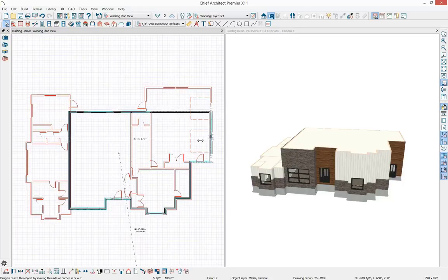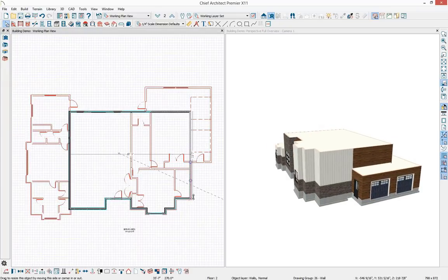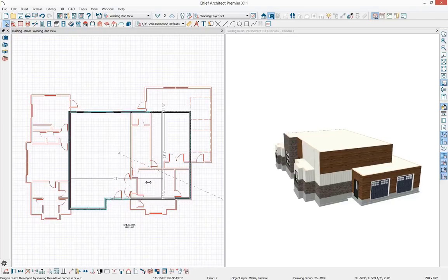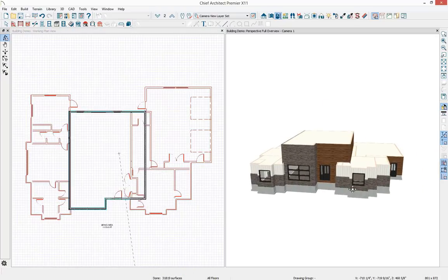And those are the wall types that I actually want to use. So I'm going to grab, if we rotate around you can see what I'm doing, I'm going to grab that horizontal paneling wall, and pull it across and pull all these walls in. And then when I pull this wall in, it'll be the wall type that I need it to be. And we'll go ahead and extend this siding wall out, and that'll finish up our second floor walls.